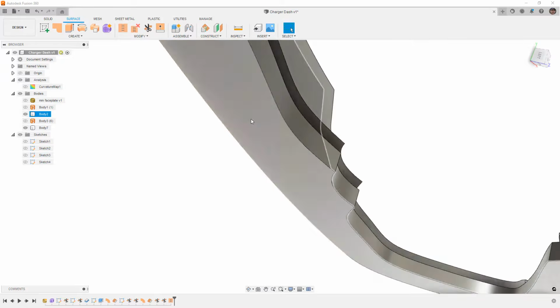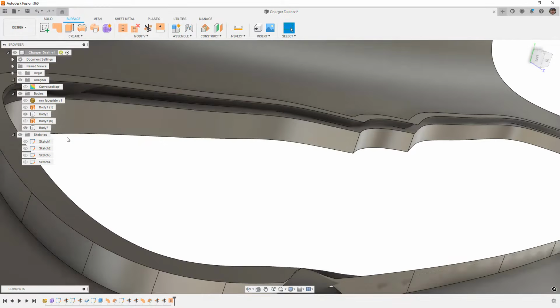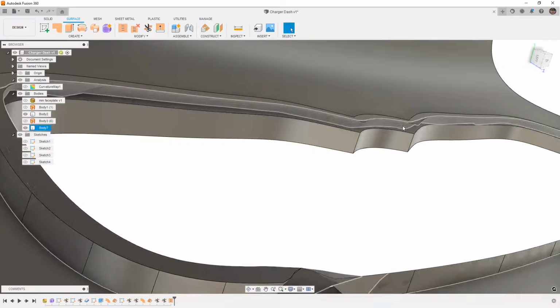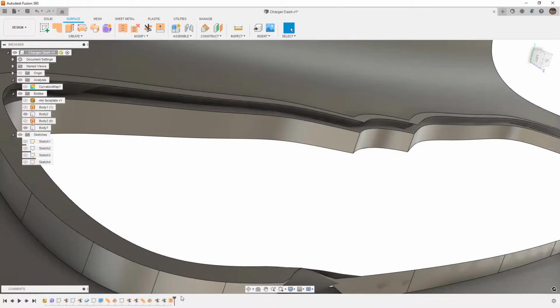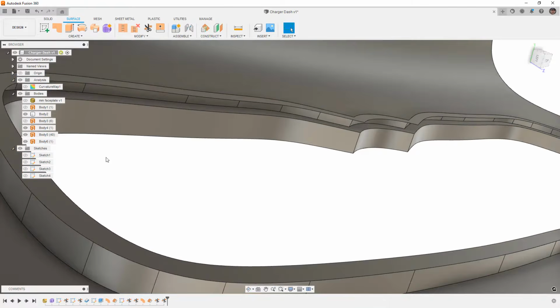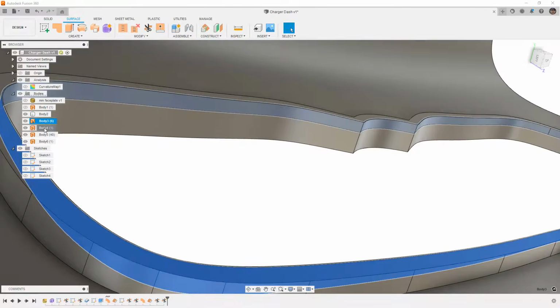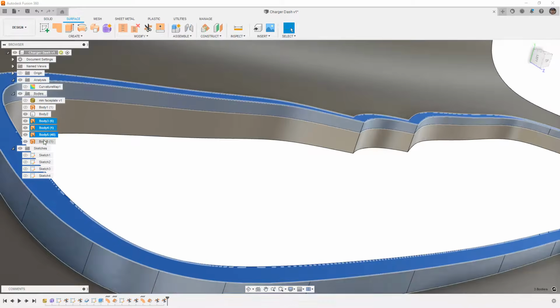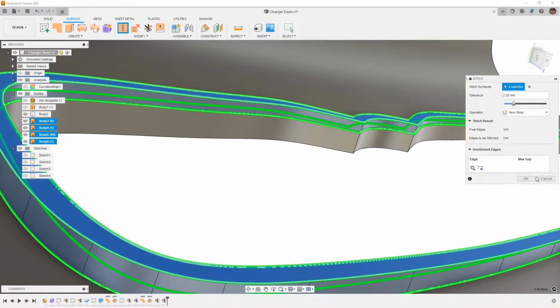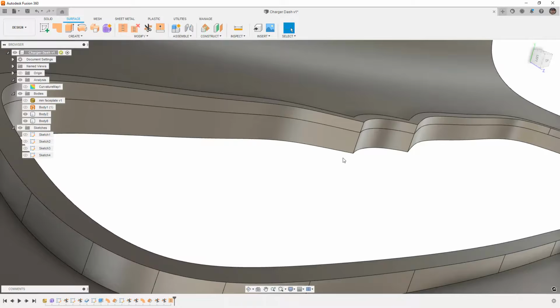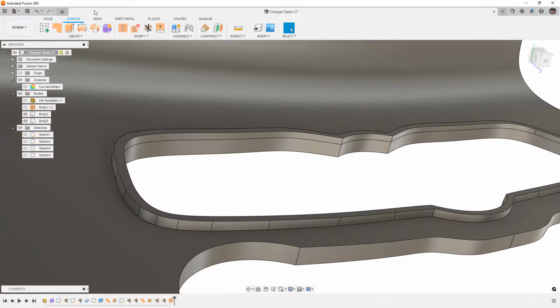And that solid body will allow us to join those together. You can see there's like this weird remnant here. Let's go ahead and unstitch that last one. And it looks like these should all create a solid body. I'm going to try to stitch it one more time. Say okay. All right, that looks a little bit better. I must have just missed a selection before.